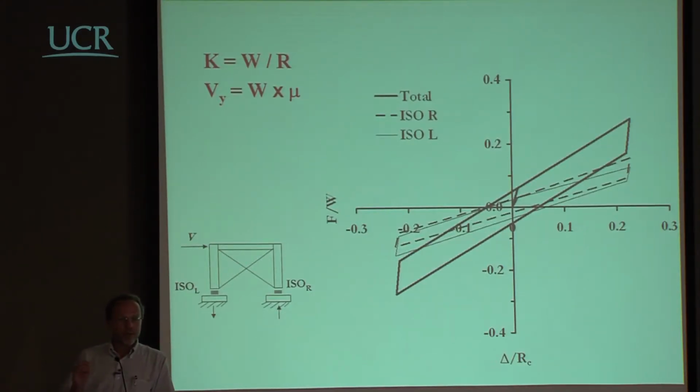Now, the problem here is, again, that if you want to do things in a proper way, and very few people in the world have been recognizing this, the crucial point is that if you want to check the upper structure, you should consider the static friction. The maximum force that your structure is experiencing is due to the instant when you start the movement.